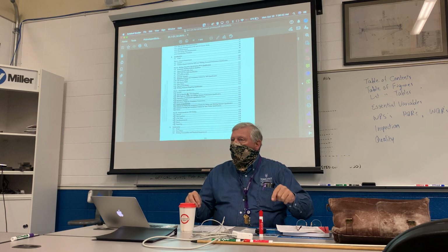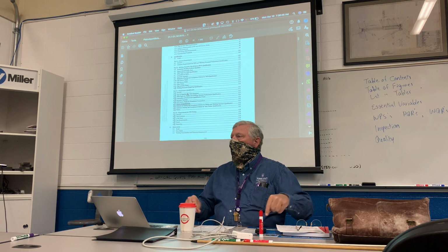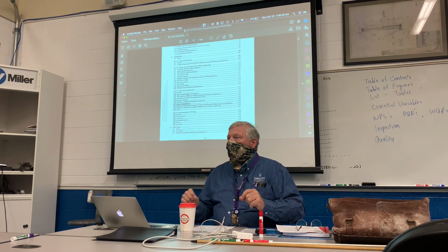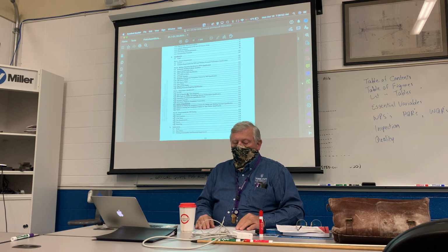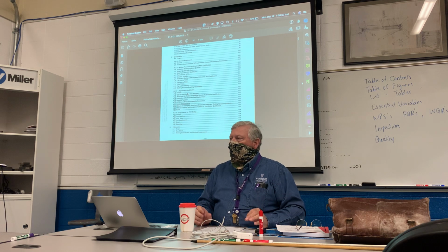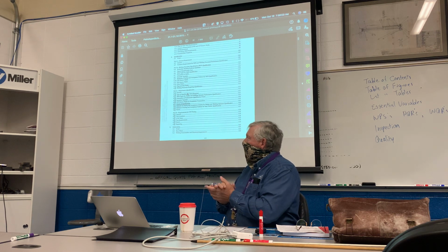But in ASME and in D11, there are specific lines that say, no, you can't do that. Each company has to qualify their own procedure. So that's the one good thing, bad thing about API, depending on how you want to look at it. But it's pulled us out of a couple of holes here and there.